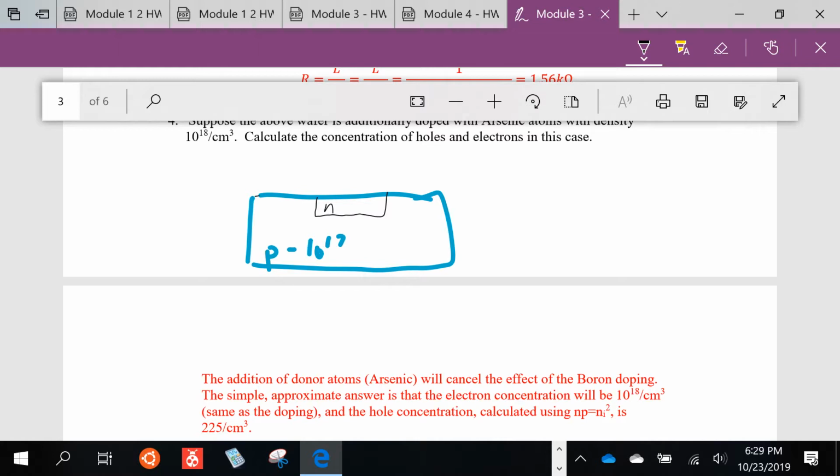So you take the silicon, you put it into a melt, and when you melt it, you can actually add your dopant atoms at that time. And then you pull out a seed crystal. The atoms add to that seed crystal, so it forms a nice crystalline structure as you're slowly pulling it out of that hot melt, and you end up with a big tall cylinder called an ingot, and it's all single crystal silicon. Now you've created that, and you slice it up into small wafers. So that's how we got this. This is from the ingot.